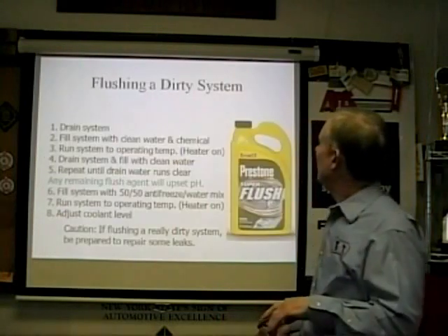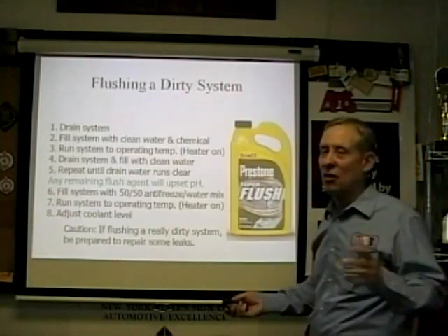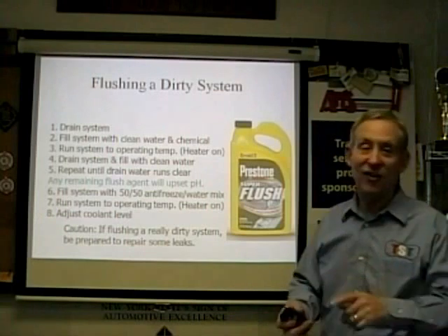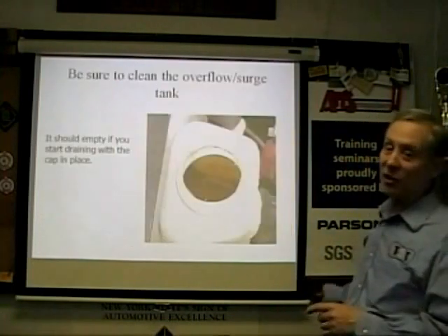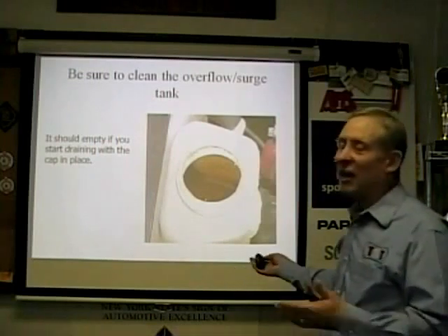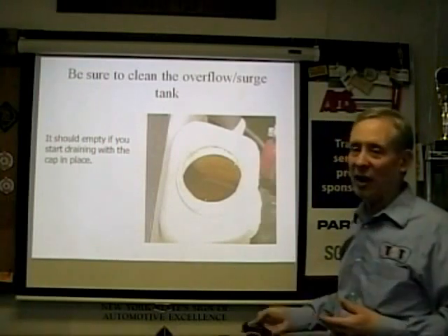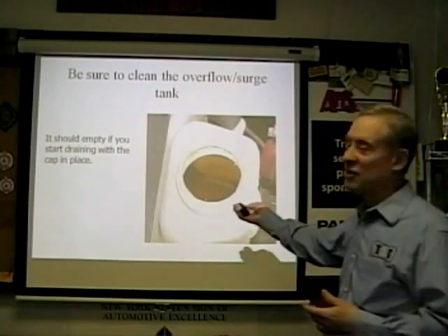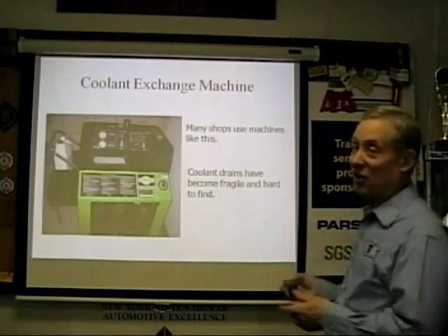All right. Flushing a dirty system. This is all kind of basic. Flush it, flush it, flush it, and put in the right stuff. Don't mix nothing. All right? You've got to clean stuff out. Make sure it's all empty, make sure it's all clean. If it's got crud in it, take the damn thing off and flush it out.